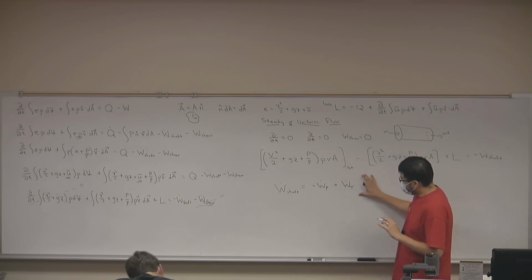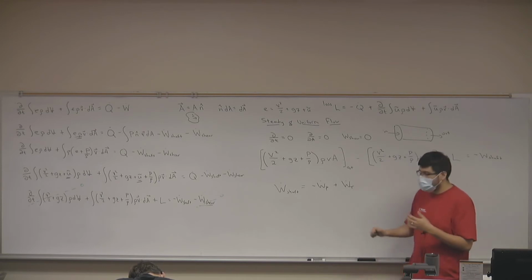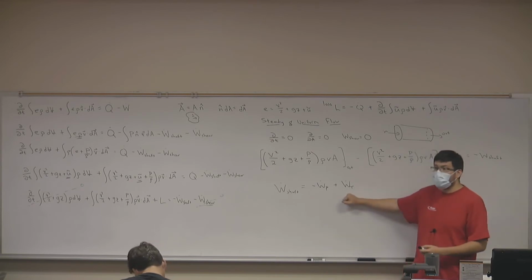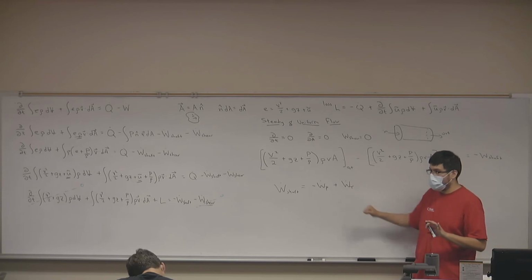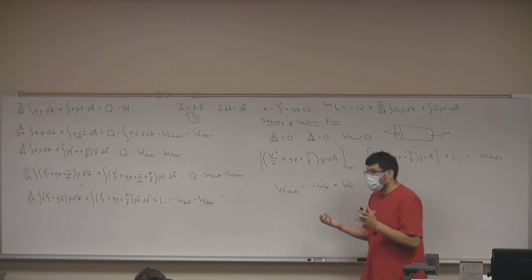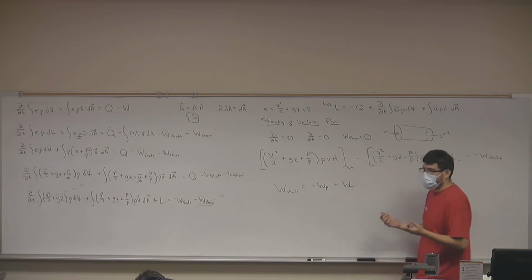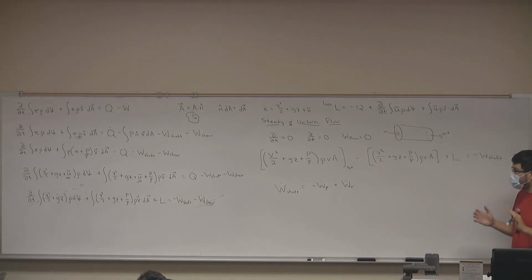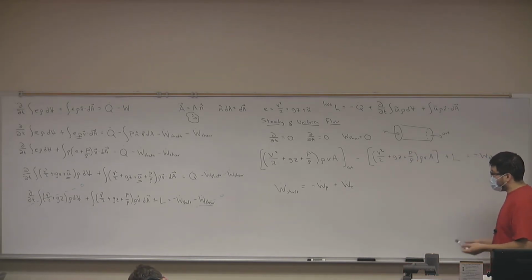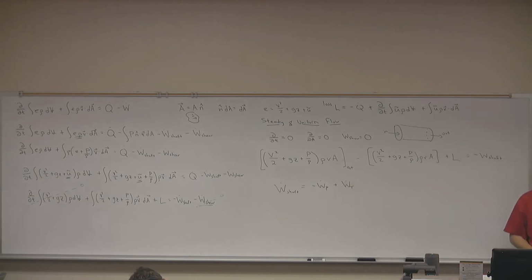Now, just because we call them pump and turbine doesn't mean that it has to be a pump or it has to be a turbine, right? We're just giving these names to represent any shaft that adds energy and any shaft that removes energy. Is that correct? So I want to make that clear, right? The propeller of a ship adds energy to my system, right? So we can consider it pump power, even though it's not technically a pump, okay? So we're using these terms, pump and turbine, in order to represent energy added, energy removed. And of course, because it's the derivative of work with respect to time, we can call it power. So pump power, turbine power.